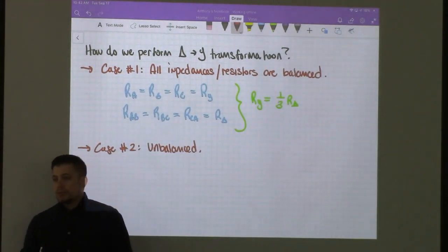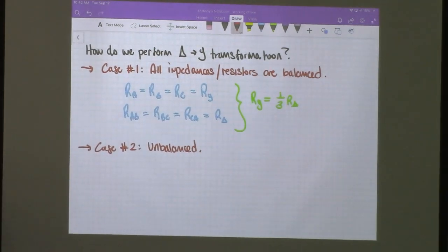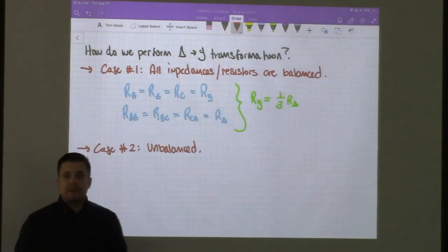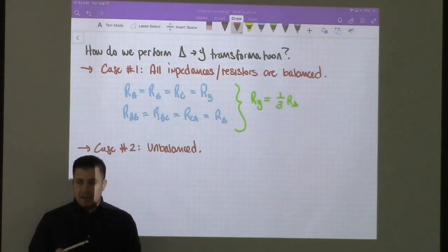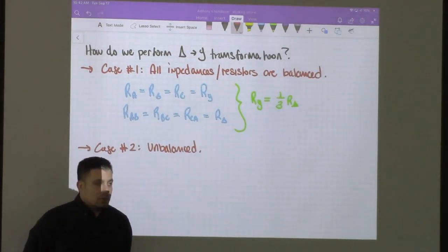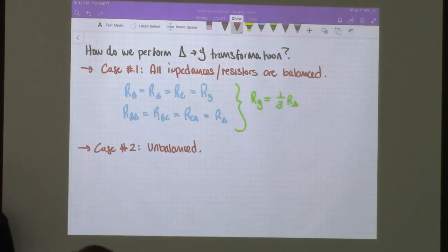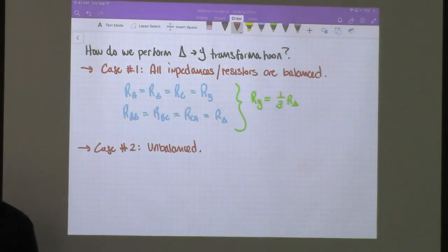All of the rules that we're applying to series and parallel combinations of resistors, delta to Y transformation of resistors, they all work for impedances as well. So later on, when we're talking about AC circuits, they'll also work. The only difference will be that then, you'll have to take into account values that have both real and imaginary parts. So when you do the math, it'll be complex math. But we won't worry about that right now.